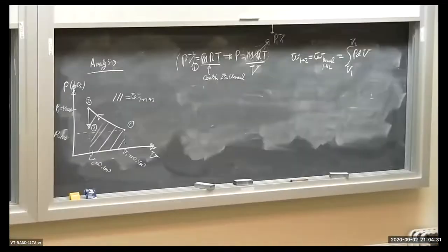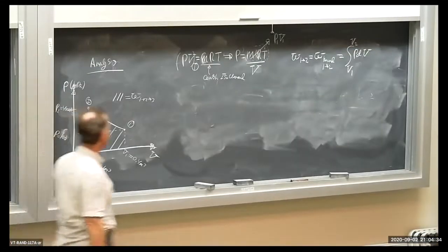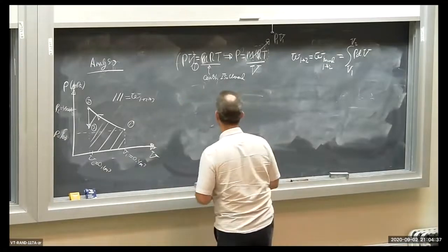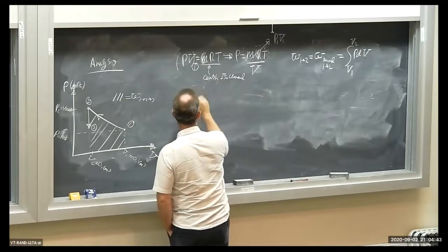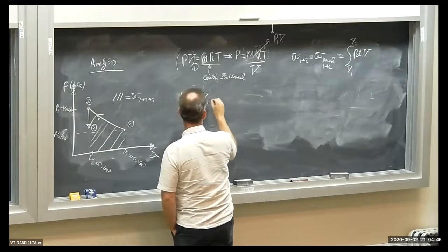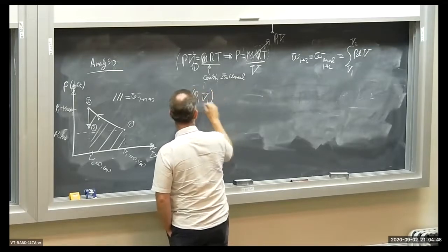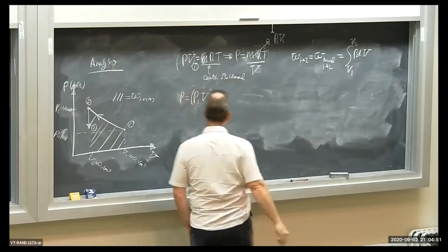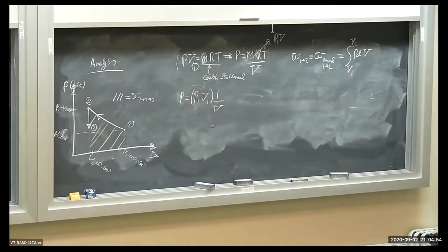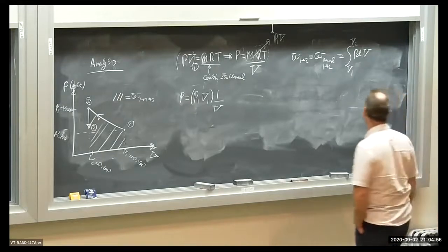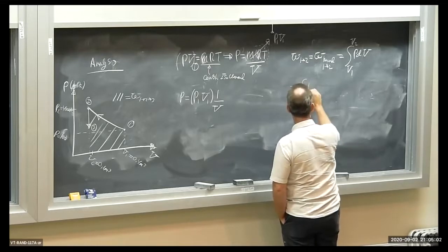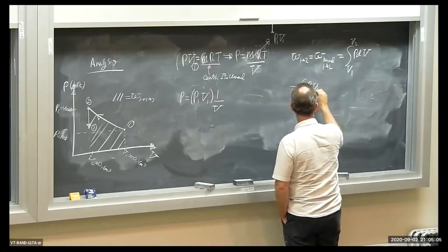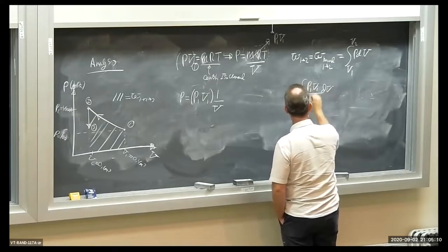I'm going to use what I know and a little bit of algebra instead of cranking out the mass. I don't need the mass. So this is going to give me pressure is equal to P1 V1, and then I have 1 over volume. That's pressure from state 1 to state 2 along the path. Let me make the substitution here then. Integral P1 V1 over volume, d volume, and that goes from V1 to V2.